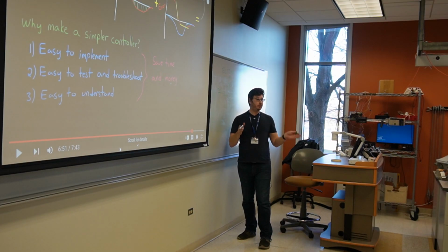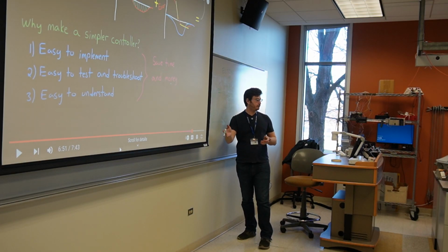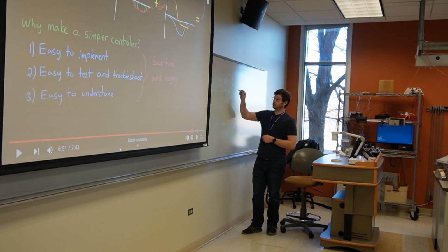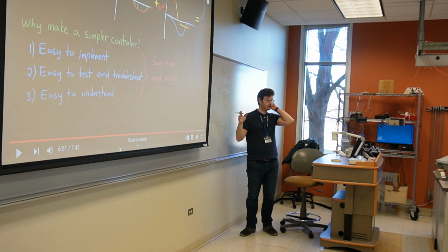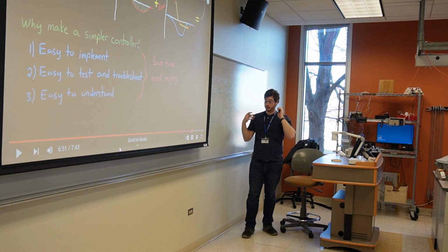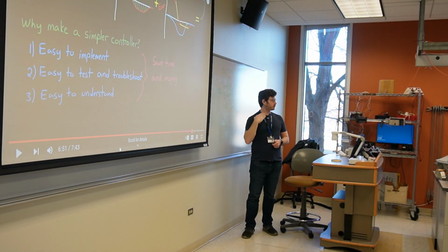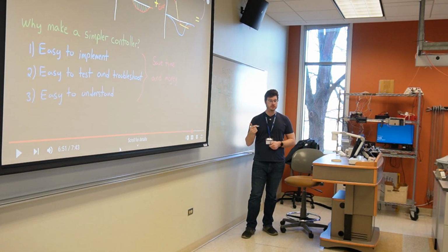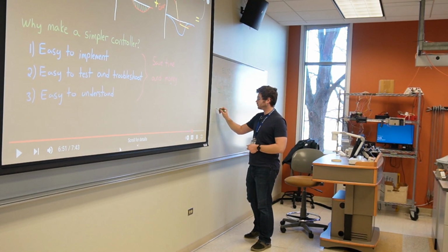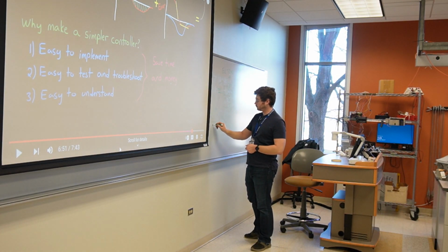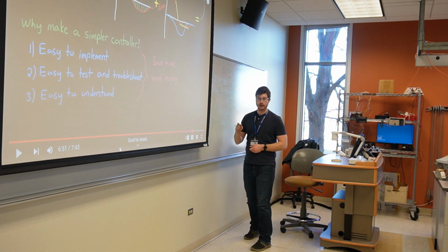If we slow down by half, it'll increase by half. If our P is set to 1, that's how we scale it. If we need to push back twice as hard as we are being pushed, we would set P to 2, and then it would respond twice as hard to any disturbances. That's all the proportional controller does. If we go this way a little bit, it responds in kind.